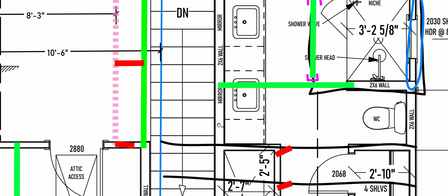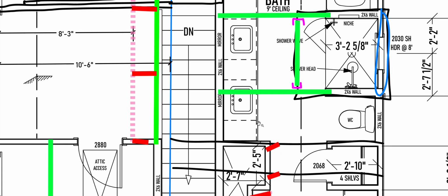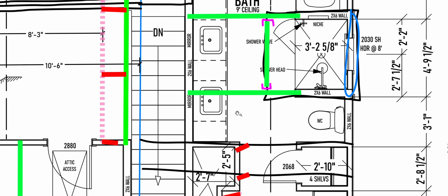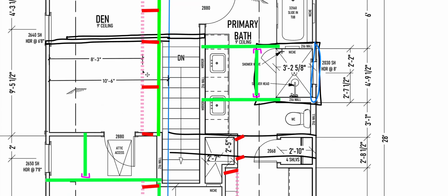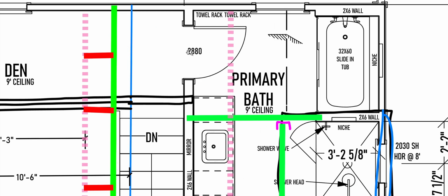I'm now going to brace on this wall, and I'm going to apply the same approximate 45-degree angle rule. So the roof slope is not quite 45. So I'm going to go to the middle between the wall and this line, and I'm going to move over slightly to the left. And I'm going to copy this guy. So somewhere about here is where I can get that purlin line and still maintain that 45-degree angle back to my wall.